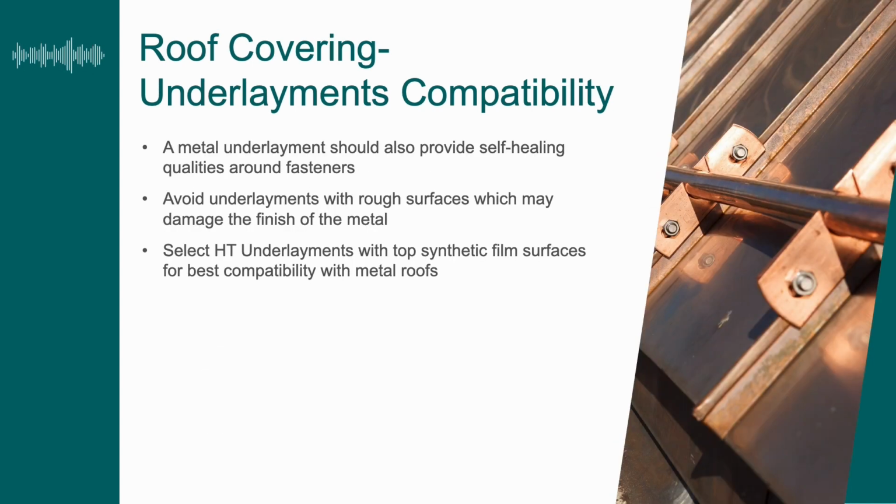Now, metal, of course, requires a whole series of fasteners and clips that penetrate through the underlayment into the deck. So an underlayment that provides self-healing qualities around those fasteners is very helpful in terms of increasing the performance of your roof system. You also should avoid underlayments with rough surfaces when you talk about metal roofing, so that, for example, a mineral surface underlayment could scratch the finish of the metal.